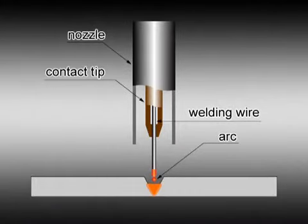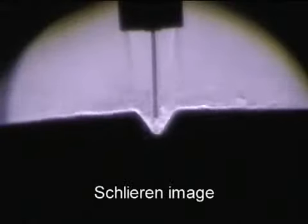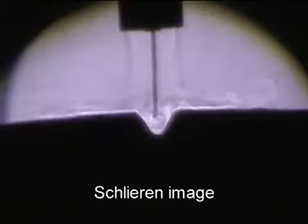Within the CO2 arc welding process, the base metal and welding wire are melted in an arc atmosphere that is covered by CO2 shielding gas. The shielding gas flows through the nozzle of the torch and protects the molten weld puddle. If this did not occur, the molten puddle would become contaminated and defect-prone due to the reaction it has with the atmosphere, which contains oxygen and nitrogen.